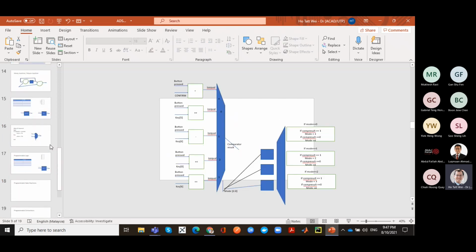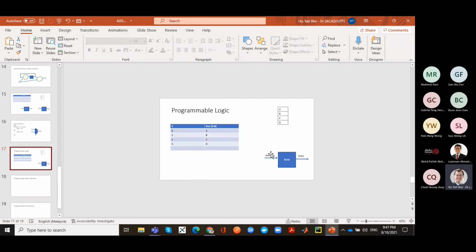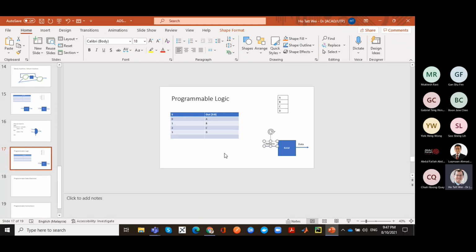Let's say you want to implement an adder. If you've got an 8-bit address, for instance, you can consider this a 4-bit adder. The MSB is the first 4 bits, and the LSB is the next 4 bits. So if I have address 0, you can interpret it as the first input being 0000 and the second input to the adder being 0000. So the data that you must send out will be 0, because 0 plus 0 is 0.